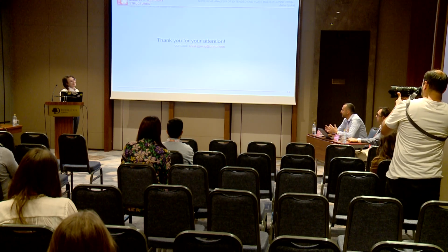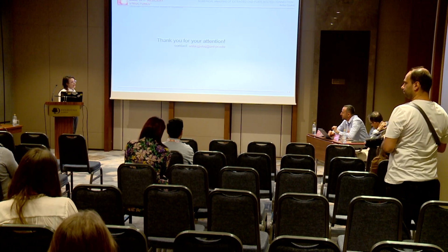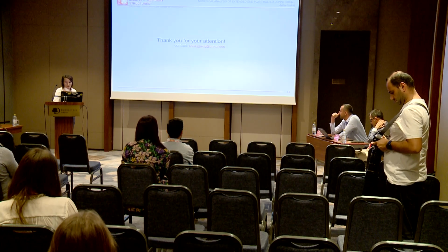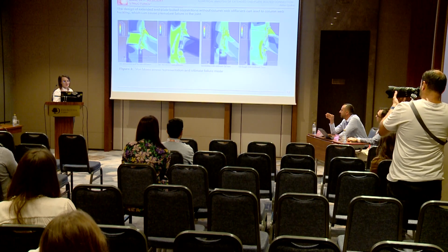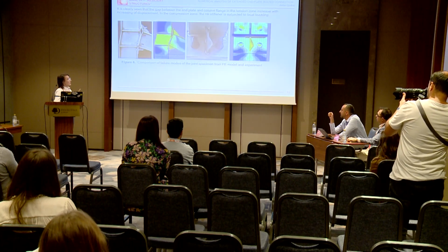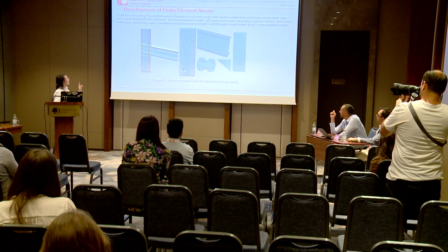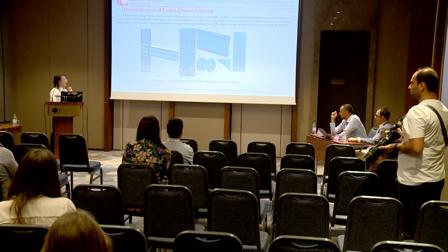How did you decide to use 3 elements through the thickness of the web and flange? I saw on the slide you said the elements were 25 and 20 millimeters. In the column and the beam, the mesh size was 10 and 20 and 25 millimeters.